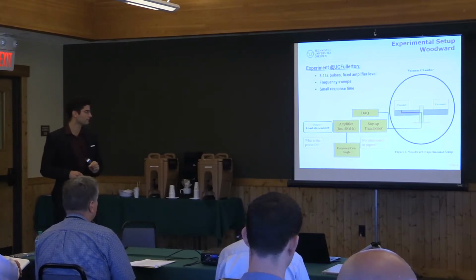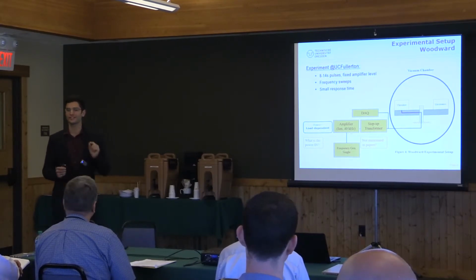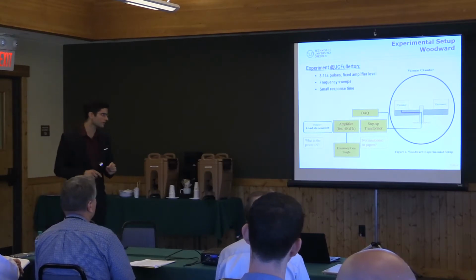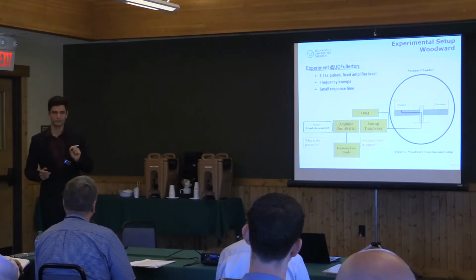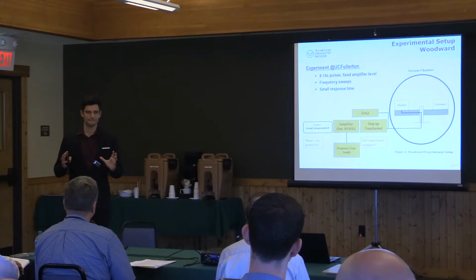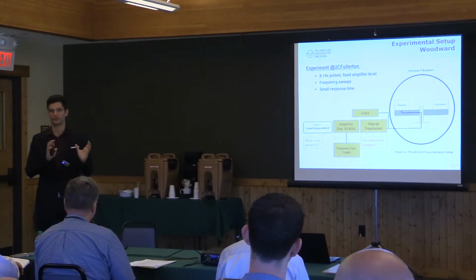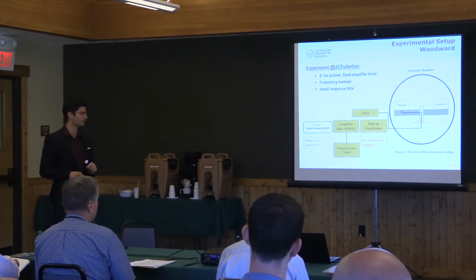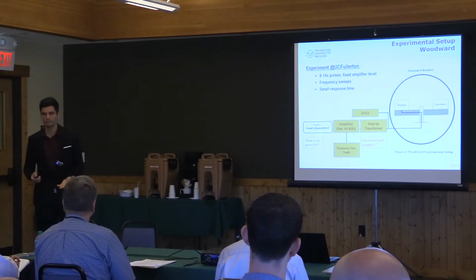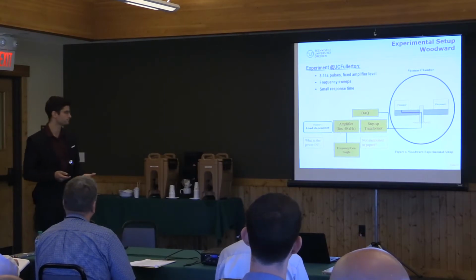And the power that it delivers is load dependent. And the load will of course change with the impedance of the thruster, but not of the thruster only, but also the system composed of the transformer with the thruster together. That's mounted on the balance and inside a vacuum chamber. So the question is, what is the power in? Because it does vary with the frequency you drive it at.